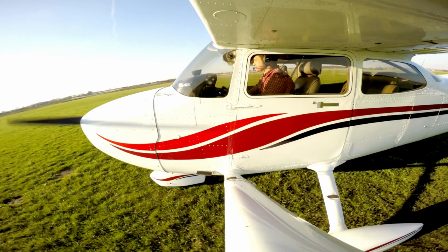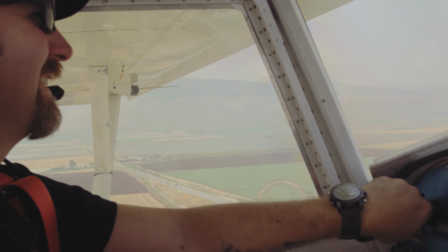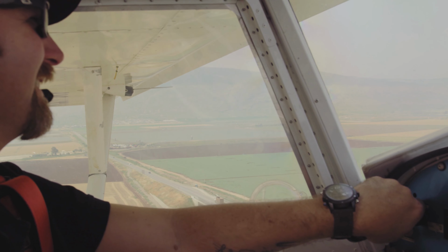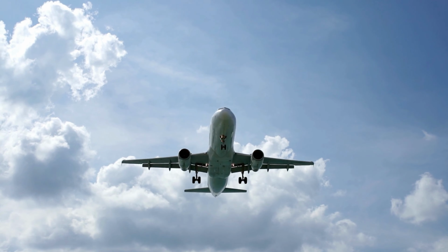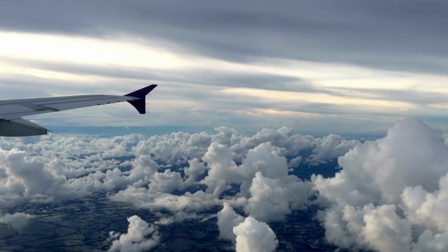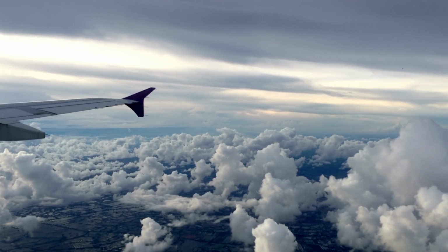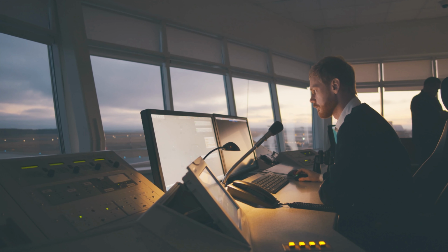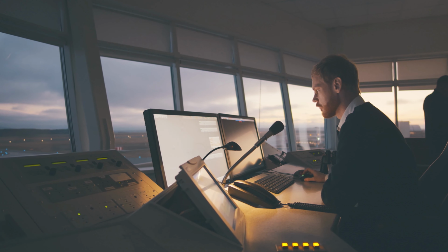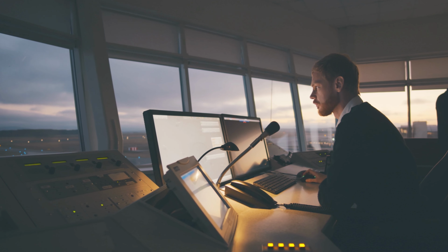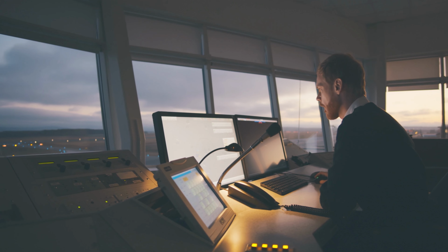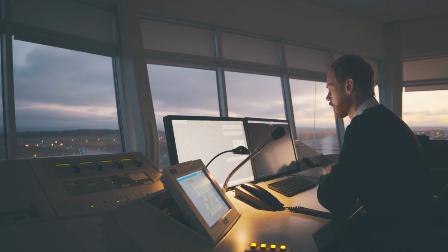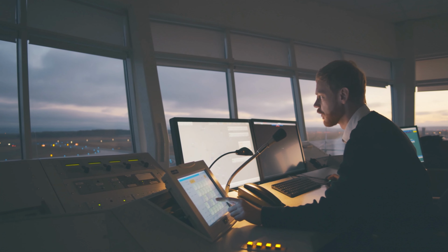avoid that as well. A little extra situational awareness doesn't hurt though, and if ATC notices your flight path crosses someone else's wake, they advise you of the position, speed, direction of flight, altitude, and aircraft type to give you a better idea of where and how intense their wake might be. ATC can also remind you to exercise caution, wake turbulence, and you'd be well advised not to take that warning lightly. An absence of ATC warnings doesn't mean you can assume your flight path to be clear of wake turbulence.